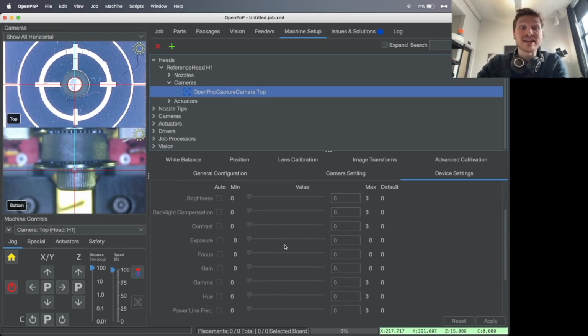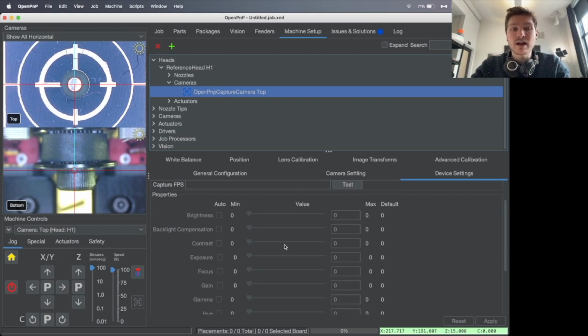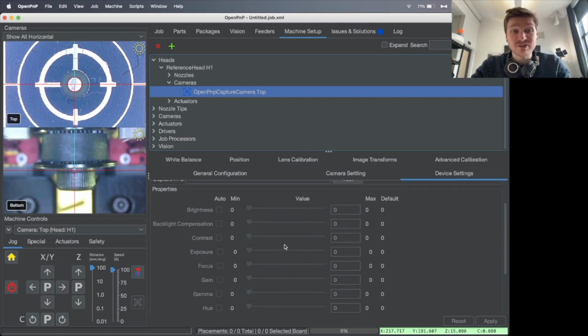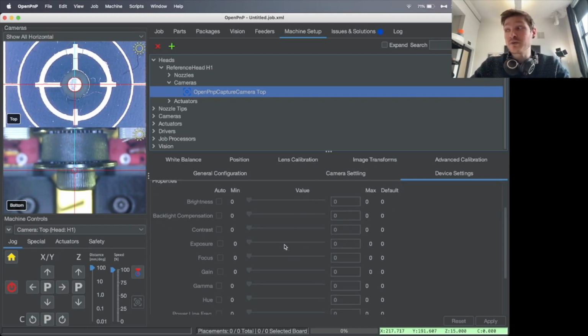We picked a camera that does have the ability to communicate over what's called UVC, which lets you set these settings, but OpenPnP does not support this for Mac for some reason. I find that the auto exposure on the cameras is okay enough for me running this with a Mac, but if you'd like to set them manually, there is an application that we recommend in our docs page that lets you manually control it outside of OpenPnP, so there's a link for that at docs.opulo.io.